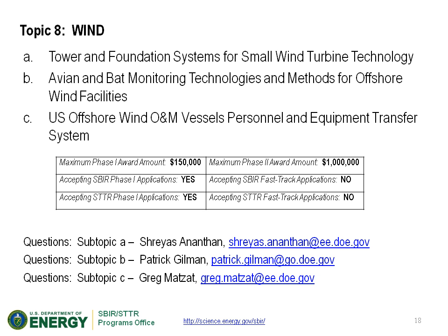Offshore wind support vessels need to be able to access wind turbines for scheduled and unscheduled maintenance. And the current technology in Europe restricts the operational window of O&M vessels to waves between 1 and 1.5 meters. And the resulting wind farm accessibility in the North Sea is between 40 and 60%. This low accessibility can reduce the wind farm availability. And this reduction in availability will lead to increased O&M costs and reduction in revenue because the turbines won't be operating.